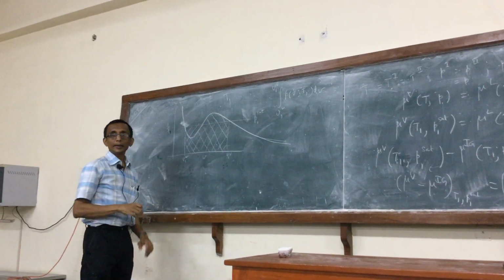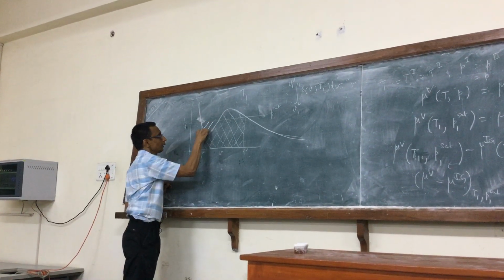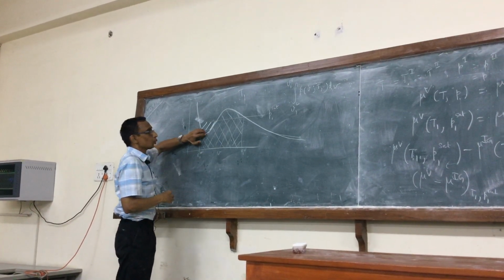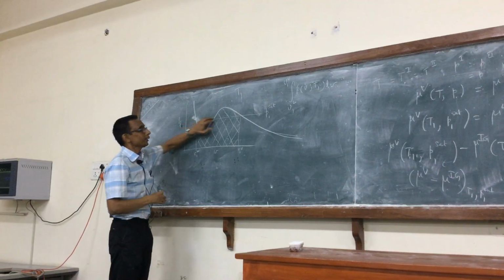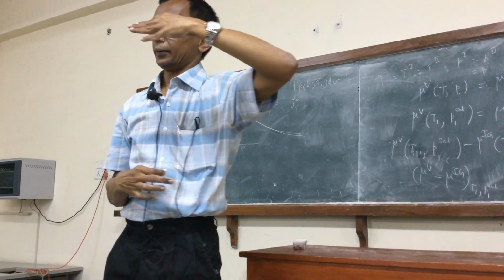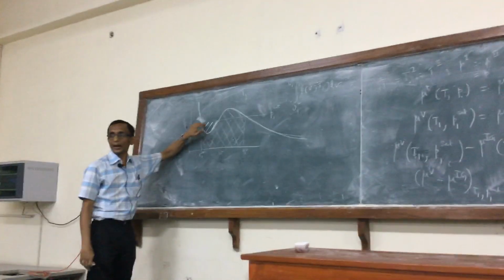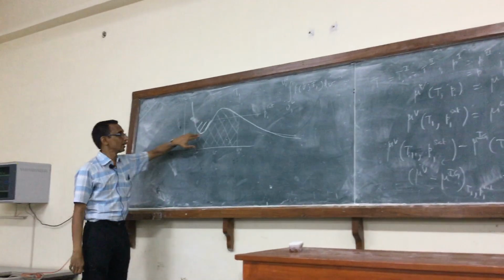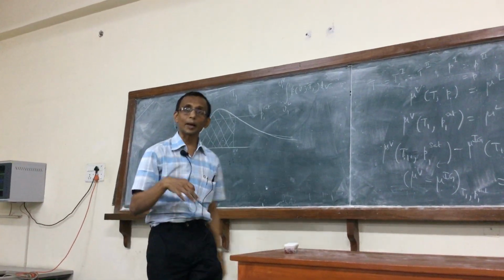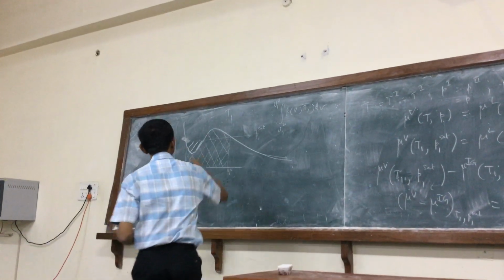The only areas that do not have a crisscross are this area, just above the P versus V curve and limited by the P equal to P1 sat line. It is the area between the P versus V curve and the line P equal to P1 sat. That is actually coming from the rectangle, not from the area under the curve. The other area, which is entirely coming from the area under the curve between V1L and V1V, is this area.